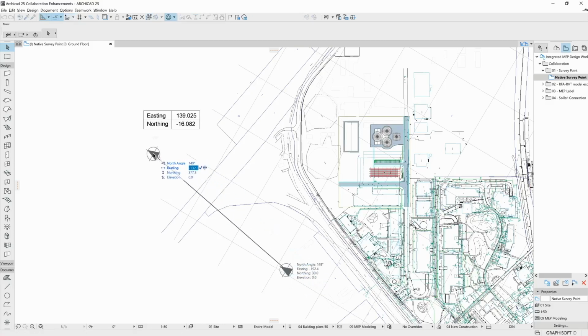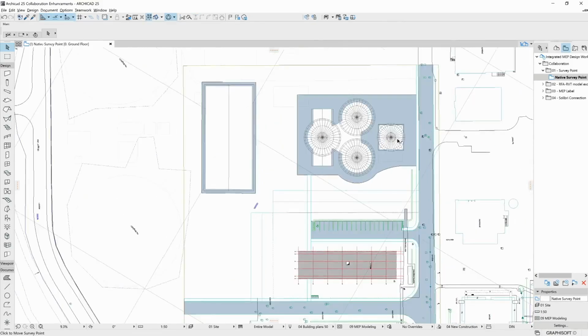These coordinates are the distance along the X and Y axis, if the Y-axis is facing true north. We can use the tracker for inputting these values. By writing the correct values into the tracker, we will relocate the survey point at the given datum in just one go.